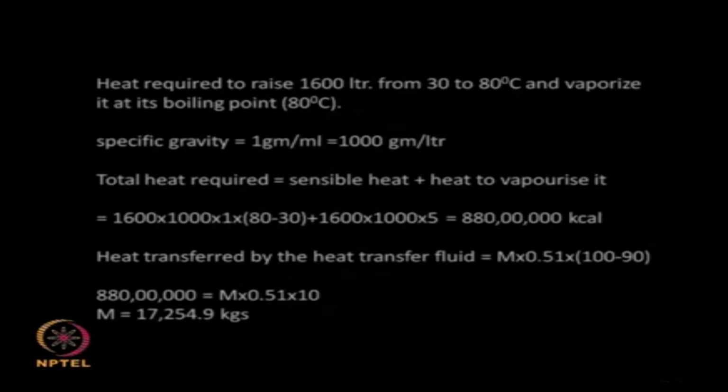So there could be some heat loss, generally we take about 10% heat loss, but we will neglect it in this problem. So you are equating this term with this term, after that you calculate m. You divide by 10, you divide by 0.51, and you will end up with this particular number. If you convert that into kg, you will get 17,255 kgs of heat transfer fluid is required to heat a